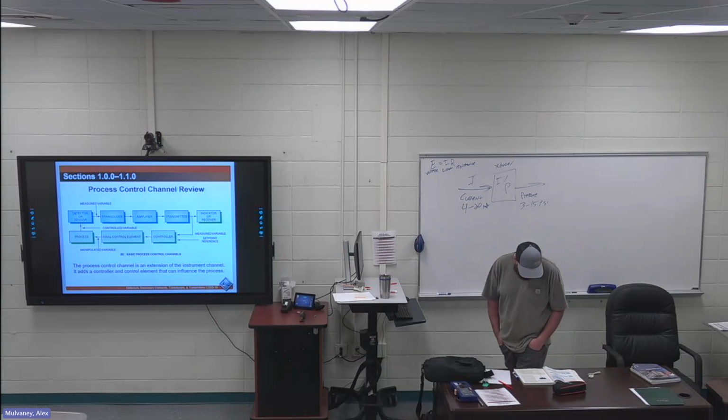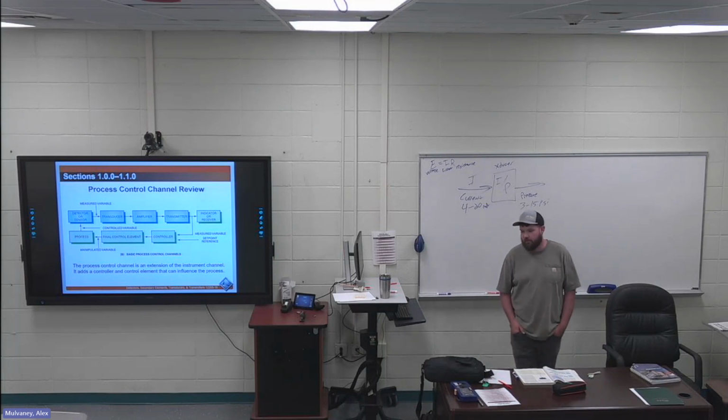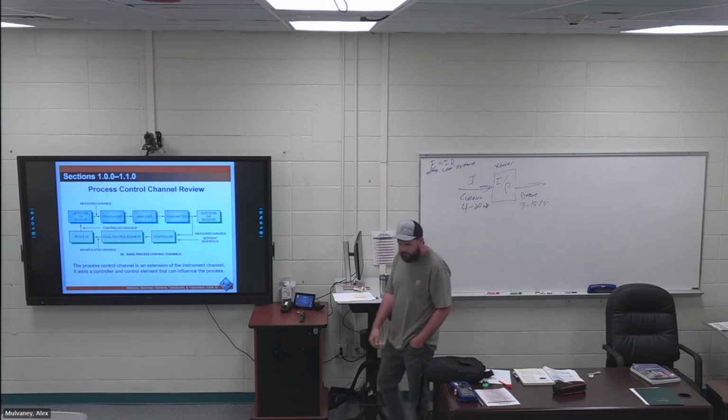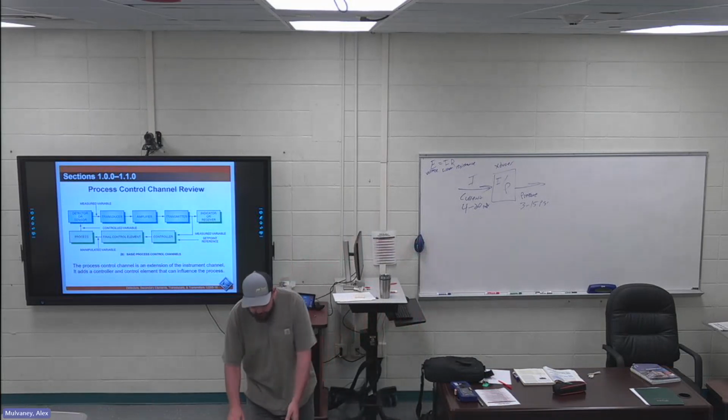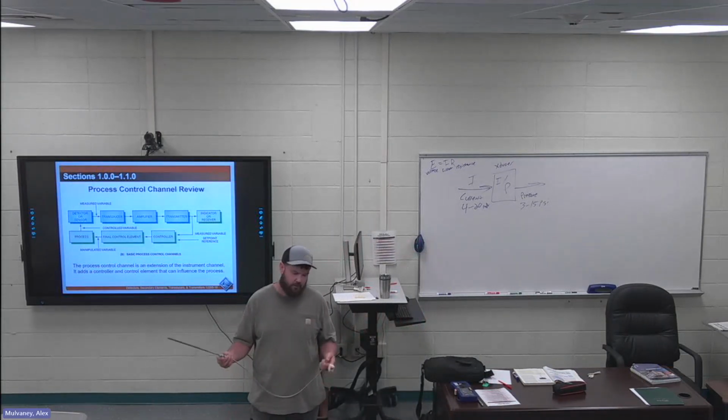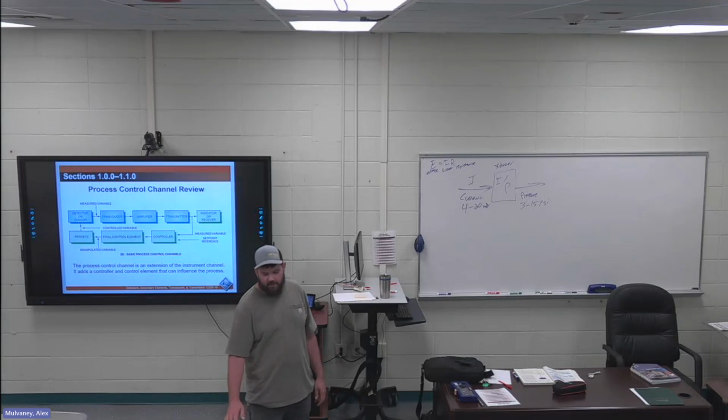Second paragraph, first sentence is highlighted. Detectors are selected for measurement systems based on the parameter being sensed, the desired accuracy, the range of measurement, and the particular type of output supplied. So obviously, for what you want to measure. Am I going to use a thermocouple to measure level? No, I'm going to get something that's for level.